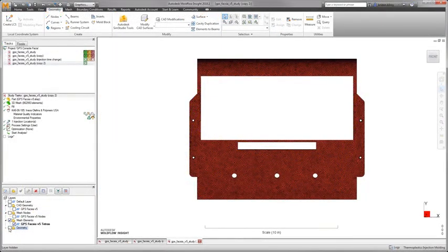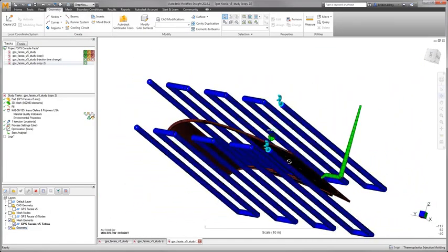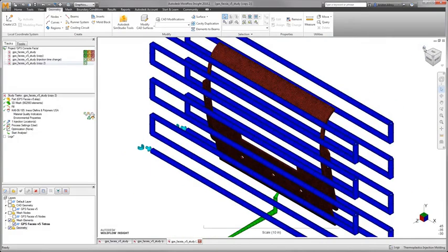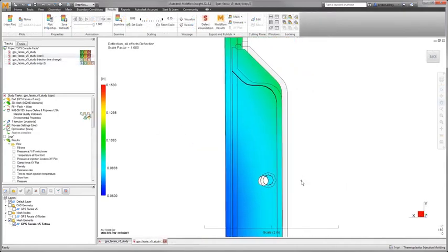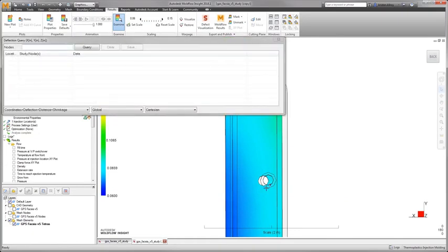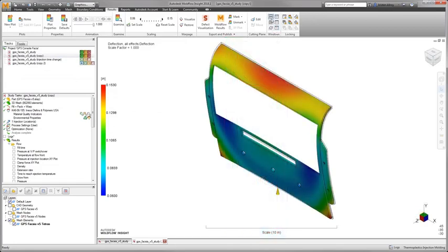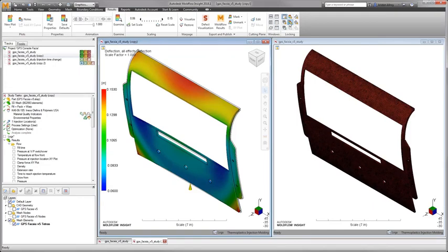When you perform a flow and warp analysis inside Moldflow, the expected deflection based on part, feed, and cool design is simulated, so you can see how much it meets with fit and function requirements per the specifications. Whether your part has an assembly or sealing surface that must be flat, features that enable you to snap or screw it into other parts, or general dimensions and geometric tolerances that must be met, understanding these constraints while reviewing Moldflow's results is critical. This is because of the options Moldflow has available to customize how warpage and shrinkage are displayed for better interpretation and comparison.